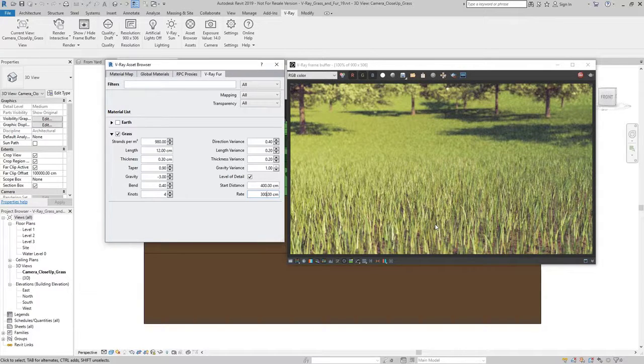In this case, here in V-Ray for Revit, we still don't have this option, so I have used an additional topo surface only at the areas that are closer to my camera, and I have assigned a ground material to it so that the ground is visible between the strands.